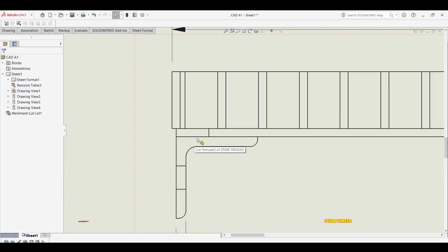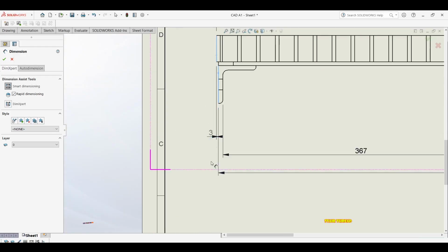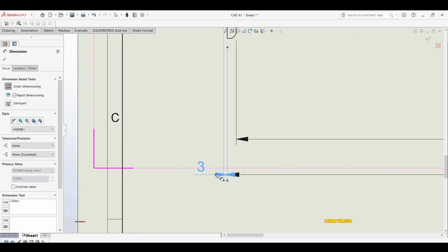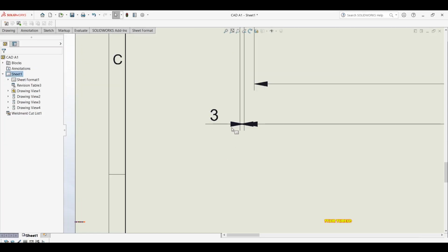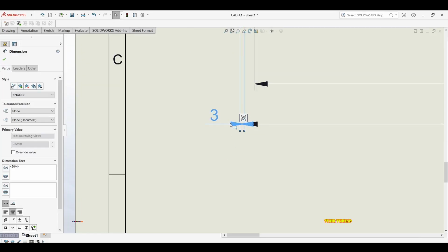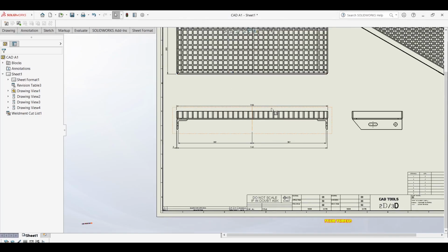If you want to, you can pull this angle iron out about, I don't know, 3 millimeters. You can just pull it and make it flush with your boundaries there.